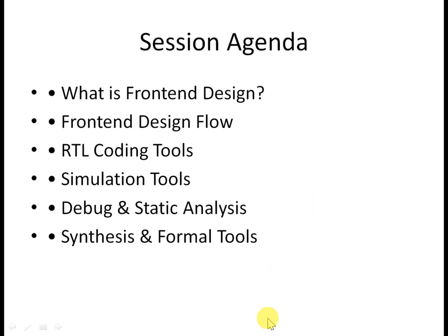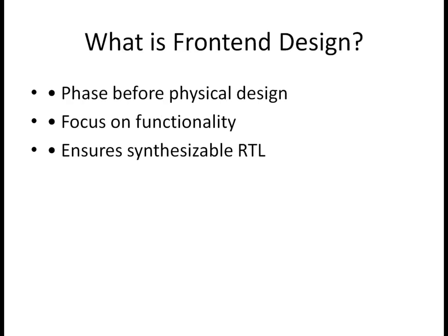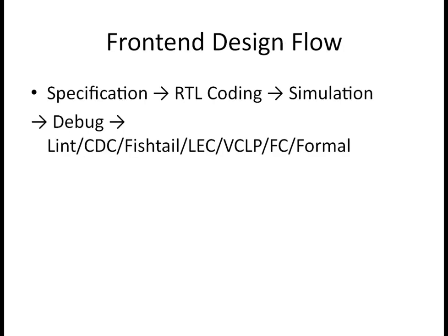So yeah, this is basically the agenda. Now, what is the front-end design flow, RTL coding tools, and so on. As I was saying, once the top level RTL is generated, the quality check tools will kick in. The first tool will be the lint tool. The lint tool makes sure the RTL coming from the integration team is syntactically correct.